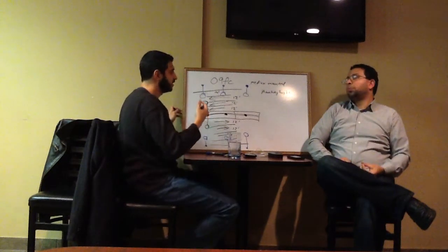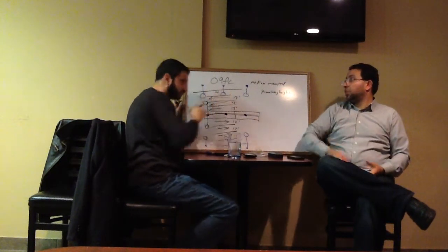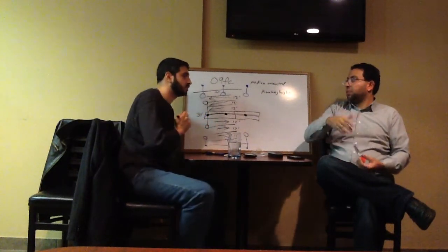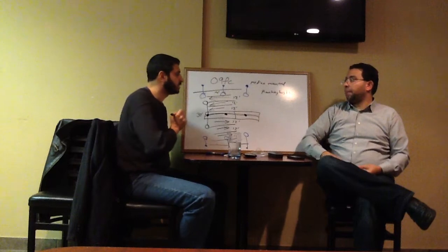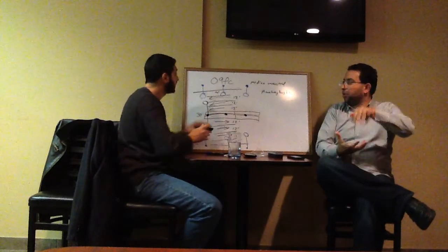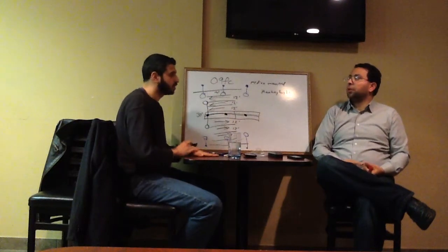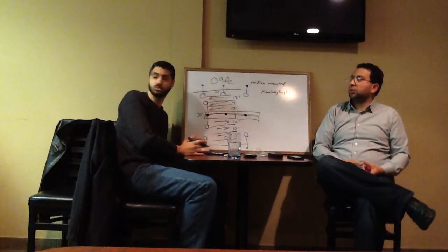Yeah, that's a good point. All the way to the top of the pavement. If there is a concrete base or something, that's part of it. If the pole is mounted on concrete, it's the bottom of the luminaire to the top of the pavement. So you've got to factor in how much the concrete foundation rises up.